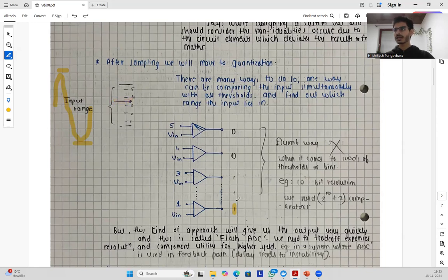So until here we have high, but the comparator gives 0 when it is lesser than the case value. So then 1 1 1 0 0. This is the digital word which will get assigned to that particular value at that particular time. So that's how we discretize amplitude. That's how quantization happens for amplitude, but it is done in parallel.